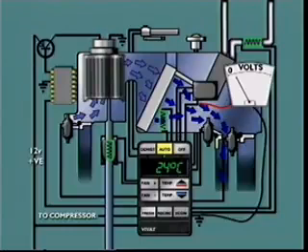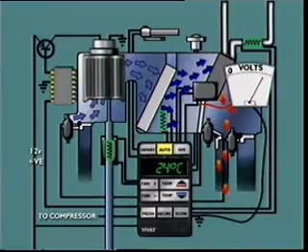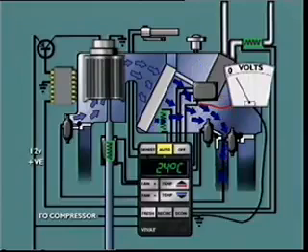For maximum cooling effect, the blend door is moved to stop airflow through the heater core, and in this position, the voltage signal back to the control unit is at its lowest value. As the blend door is moved to allow airflow through the heater core, the voltage at the signal wire progressively increases until, at the maximum heat position, the voltage signal is at its highest. The control unit is thus aware of the blend door position, movement, and direction of travel.